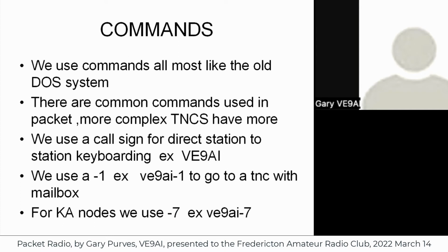Commands. A lot of the commands used in packet are like the old DOS system. There are common commands used in packet. More complex TNCs have more commands, of course, more setups. We use the call sign for direct station to station keyboarding, like VE9AI. If I wanted to connect to VE9OR, I just put C VE9OR, and it would go there and wait for Charles to come on, and we could keyboard back and forth.